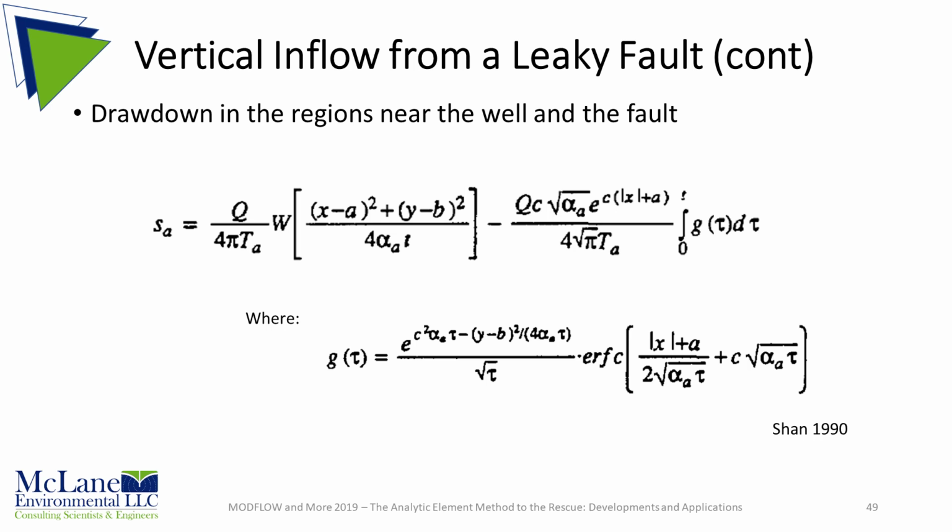A better approach, given the tools we have available today, would be to develop a simple AEM model for this situation. What is needed to represent the fault is a linear element controlled by a reference head, that is, the water level in the upper zone, and which yields water through some resistance, the degree of sealing within the fault, when the well is pumped. That is exactly what an AEM river element does.